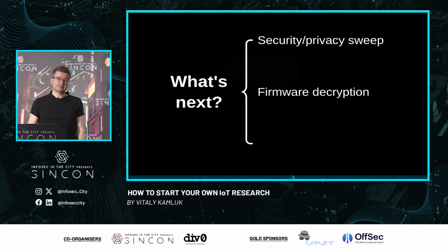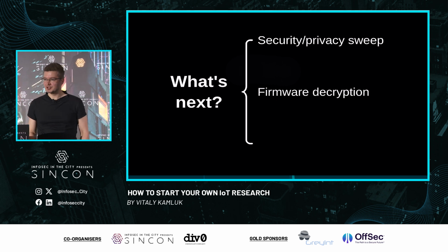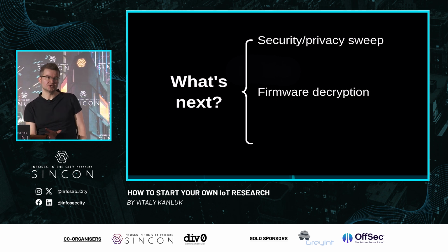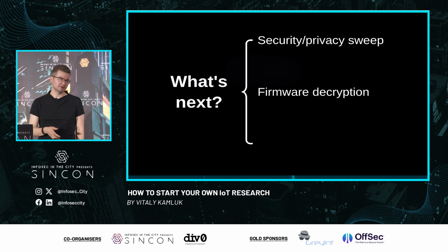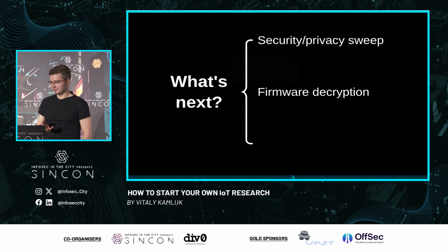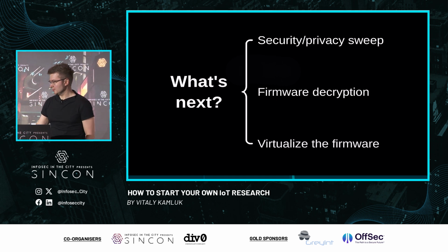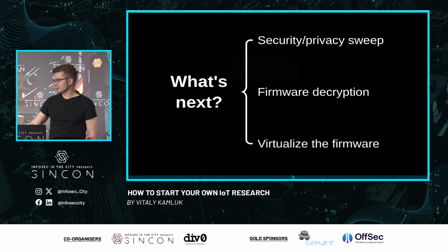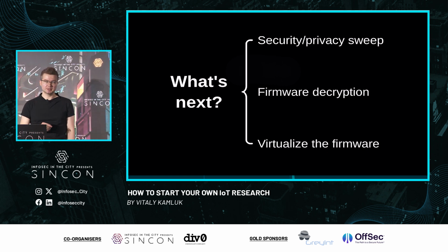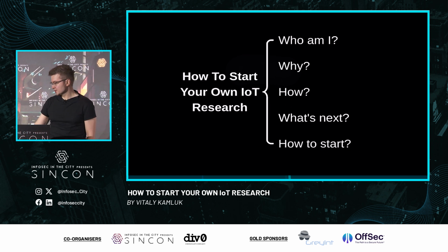Then you can even work on further firmware decryption because now you have access to a real running system. You can initiate upgrade, you can debug the process, you can see which encryption keys are used and what the format is. You can really not just do static analysis, but do dynamic analysis through running a debug server right on the device. Although that's a MIPS CPU and architecture, so be prepared for that. And then eventually you can even try and virtualize the firmware once you understand how exactly it works and what the requirements are to initiate the device in the working stage.